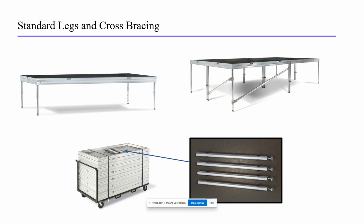Standard legging is great for stadium overbuilds when you're spanning the platform over an existing concrete tiered bowl to create an ADA or camera platform around the concourse of a stadium. They also work great in theaters for flexible seating configurations below 30 inches in elevation for their ease of use and quick setup and strike times. Of course, if you go above 30, that's possible. You just need more diagonals that cost a little bit more time.